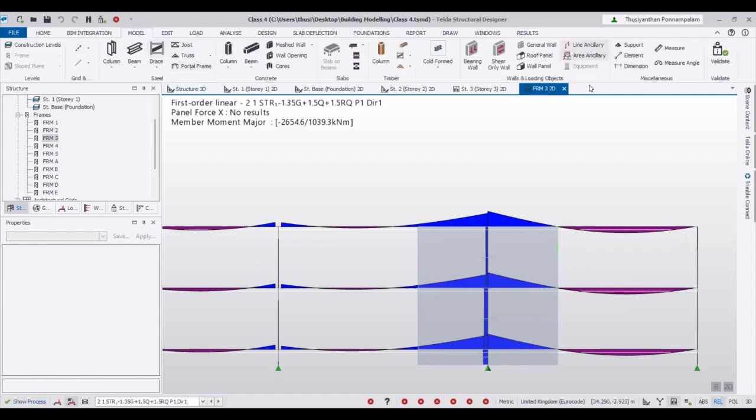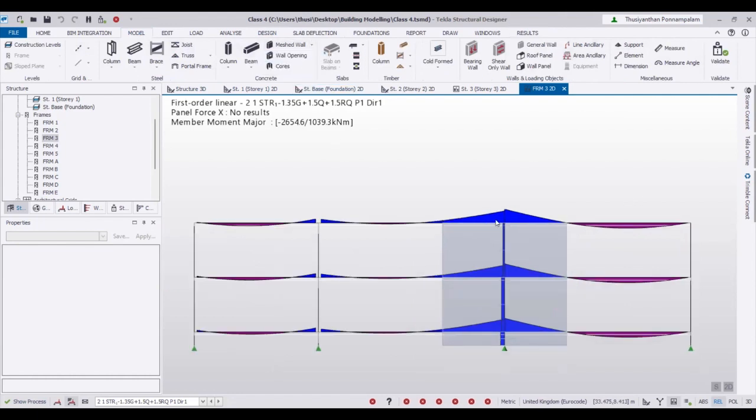you remember when you did the modeling, what I chose is mid-pier wall. That means this considers one pier at the mid and applies the stiffness of this wall, so the software considers one beam with the stiffness of this wall and does the analysis. That's why it gives the bending diagram like this.